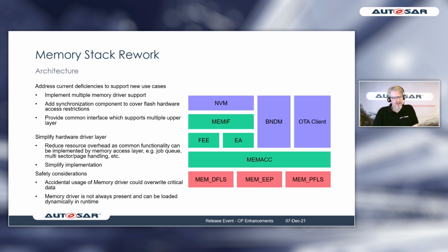But here, safety considerations are always an important topic, because if we have access to program flash, we also need to check that accidental overwriting of such program flash is prohibited.